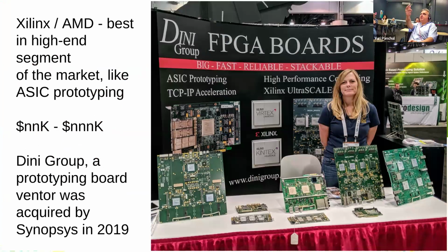This is a kind of prototyping board, which is in addition to an emulator. So instead of using an emulator, you can buy such boards which cost not several million dollars, but like 30K or 100K, and put your ASIC design in such a high-end FPGA board. But the problem with such boards is they have limited ability to look inside what is going on. With an emulator, you have a very debuggable design, so you can see every signal. And this is the beauty of an emulator.